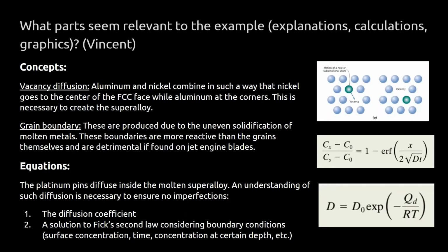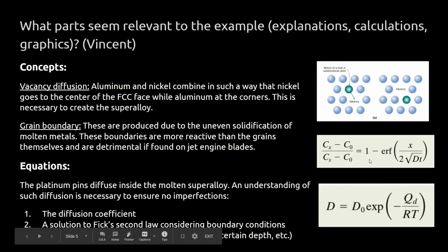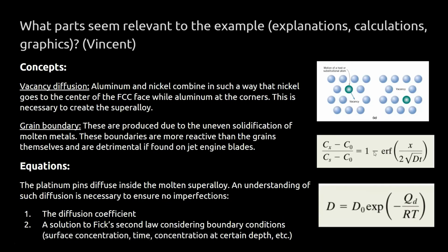Now, following with equations, while the solidification of the superalloy is taking place, the platinum pins inside the mold also diffuse into the molten superalloy. This means that it's necessary to know the diffusion coefficient, which then contributes to Fick's second law for us to understand the pertinent parameters, so that this diffusion happens well without imperfections. Also, here's an illustration of vacancy diffusion, where this space is expected to be filled by the diffused metal.